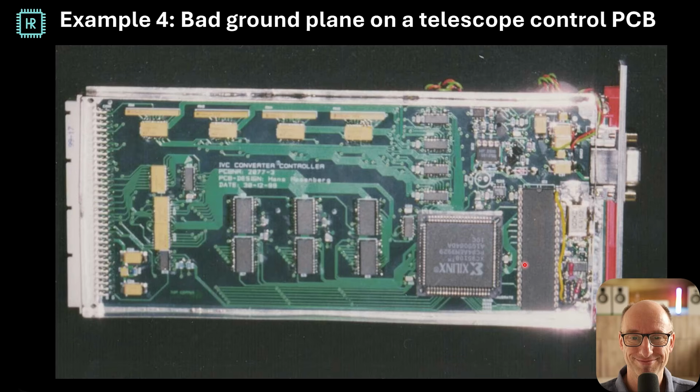So it's very important to realize that an unobstructed ground plane also implies no multiple ground planes. Always have a single ground plane. Never ever in my whole 42-year career have I ever seen multiple ground planes be an improvement. So keep that in mind.